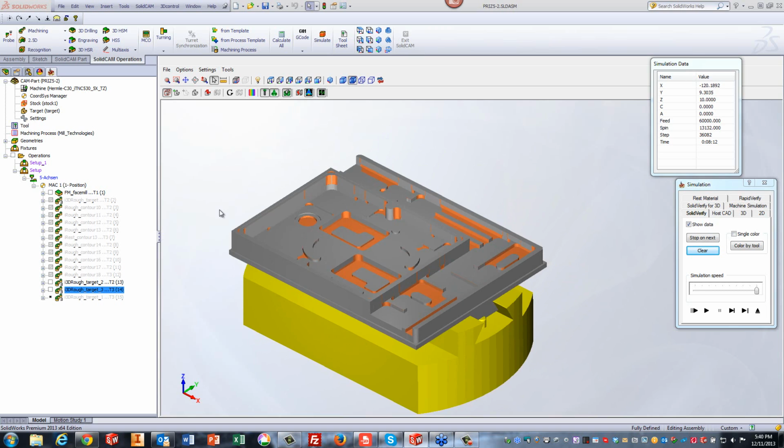These are excellent for prototypes as well. The advantages of the 2D iMachining over this is that in 2D iMachining you can actually do specific areas sometimes, when you want to do a specific area, and you have more control. But then again, you always have to remember that you have the complete control. You can make a mistake sometimes picking the wrong surface or picking the wrong geometry. You have to be careful of that.